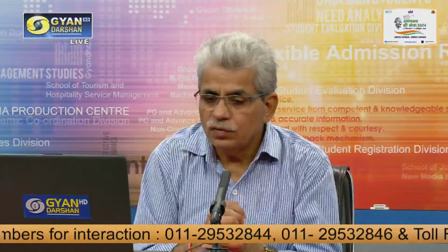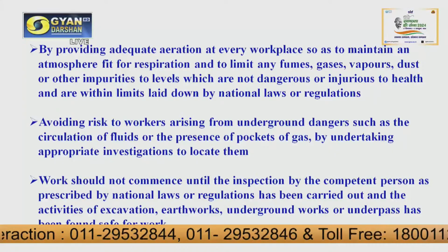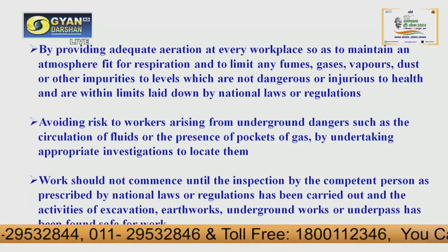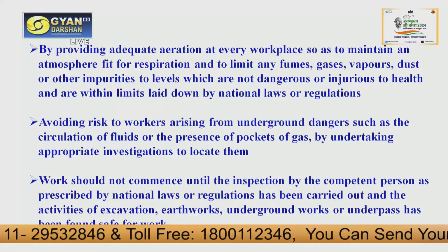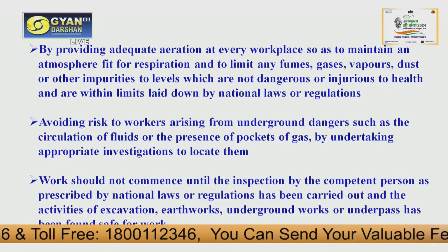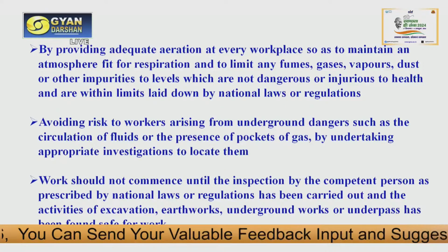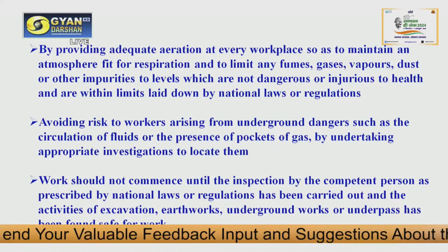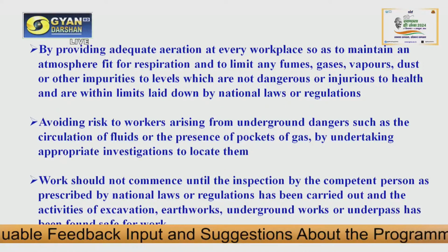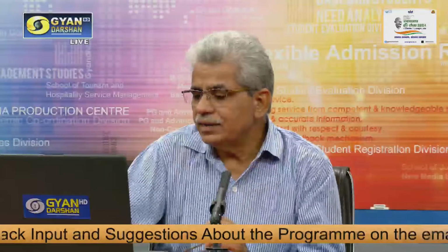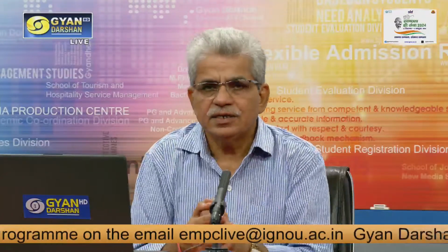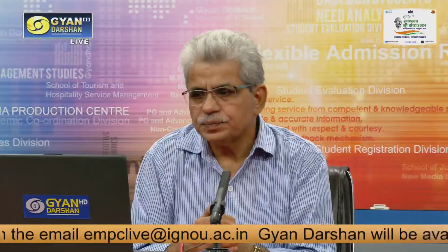Then work should not commence until the inspection by the competent person, as prescribed by the national laws or regulations, has been carried out and the excavation, earthwork, underground work or underpass has been found safe for work. So it again stresses that inspection is a must before starting any such type of work.